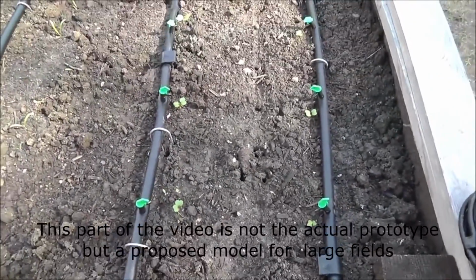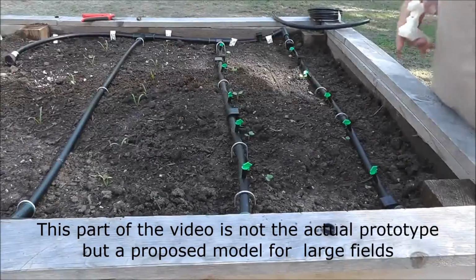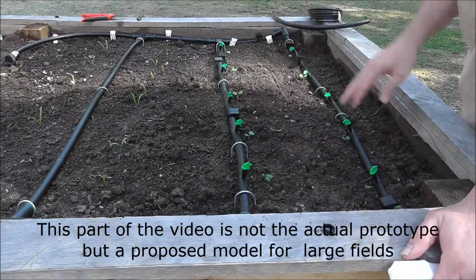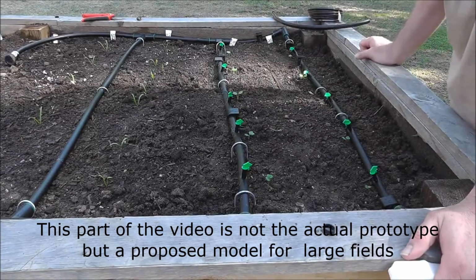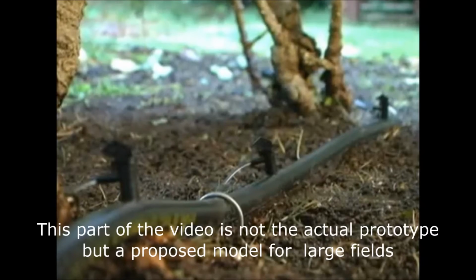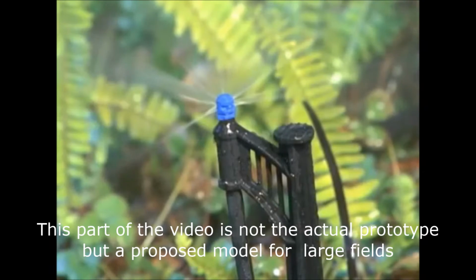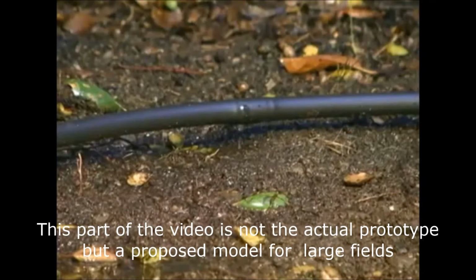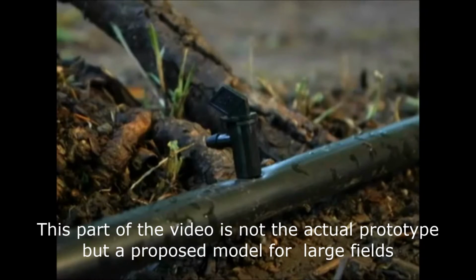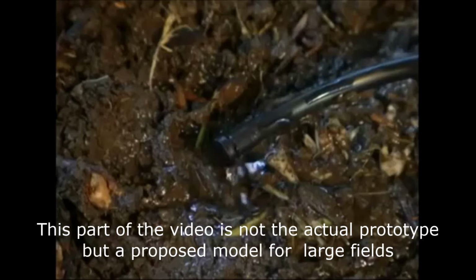Using drip irrigation is beneficial in many ways. Higher efficiency of water and fertilizer use. Better uniformity in water distribution, especially on plot edges. There is no wind influence, hence the system can be used at all hours of the day. No water waste on plot edges, thereby reducing weed growth between crop lines. Reduction of foliar diseases. Higher yields up to 25%, mainly due to uniformity and efficient fertilization. The automation of such a system will add to the advantages and thereby increase the efficiency.